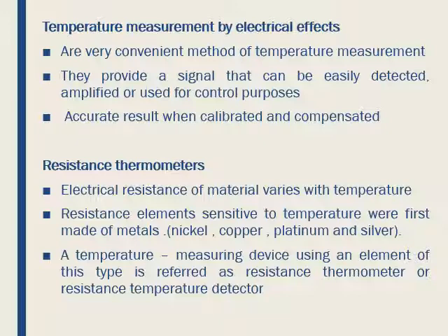The thermometer bulb is usually filled with mercury, which all of you have seen and used from your high school. It has the advantages of a broad temperature span between its freezing and boiling points, a nearly linear coefficient of expansion, relative ease of obtaining it in a very pure state, and its non-wetting of glass characteristics.